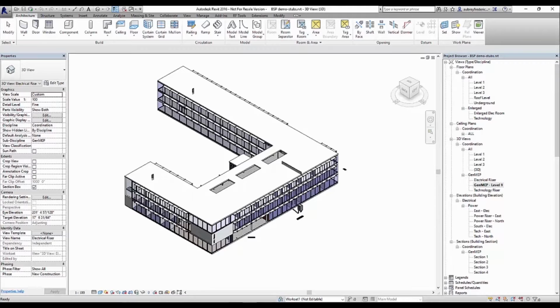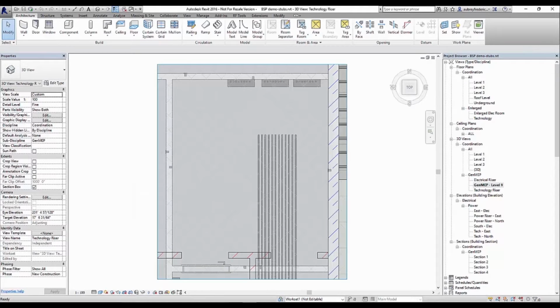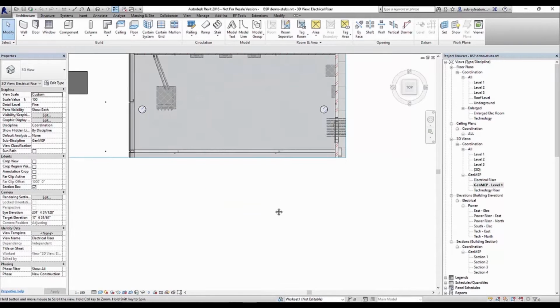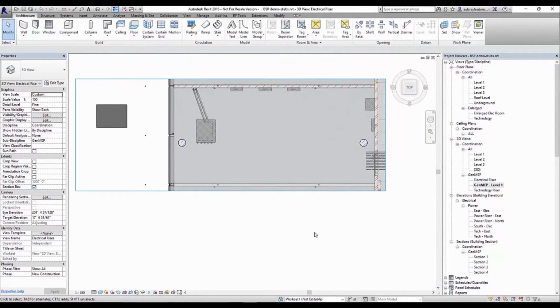So if you were to apply a little bit of front end management there with that information, go into your electrical rooms and create yourself a couple of stubs in your openings or your windows on some of your gear and equipment that matches how the designer or the foreman plans to create the conduit runs or the conduit racks.